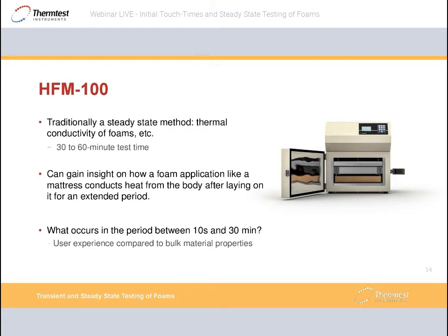Anyone who is familiar with this instrument might find that a bit peculiar, because traditionally this instrument is used in a steady state method to measure the thermal conductivity, which includes 30 to 60 minute test times. This will allow us to gain insight on foam-like applications, like how does a mattress conduct heat from the body after laying on it for an extended period.